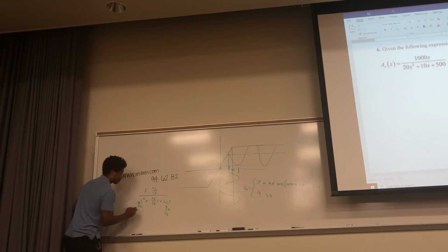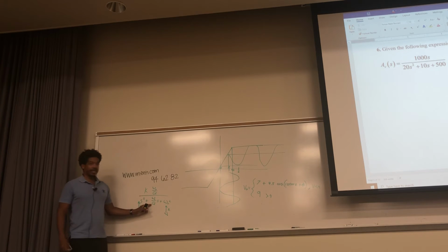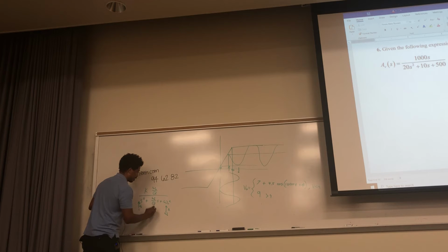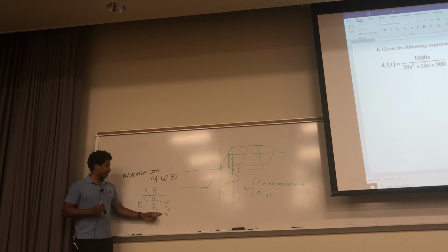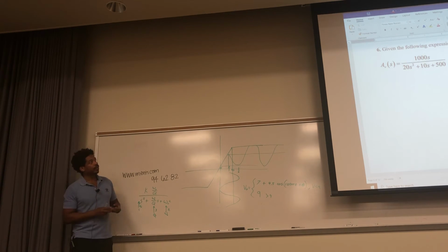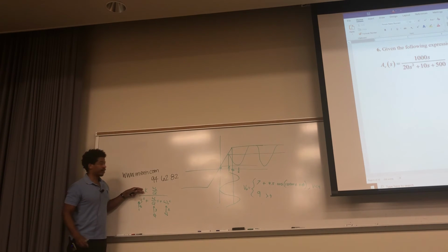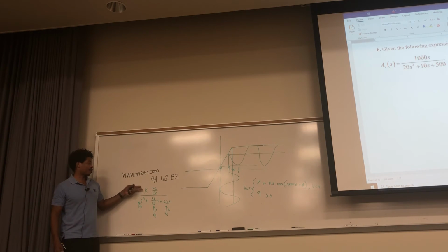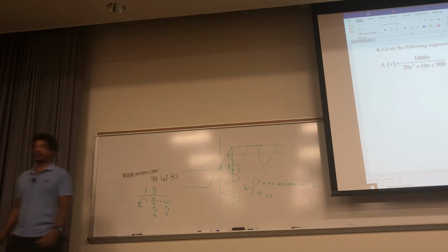Divide out. Step three is identify q by this factor that's left in front of the s, because once you identified omega, you could plug it here and then determine what q must be in order to get this factor. So this is step three, identifying your q. Once you have your omega and your q, then you can factor that out of that top numerator to find out what your a is, or your k, your multiplication factor.